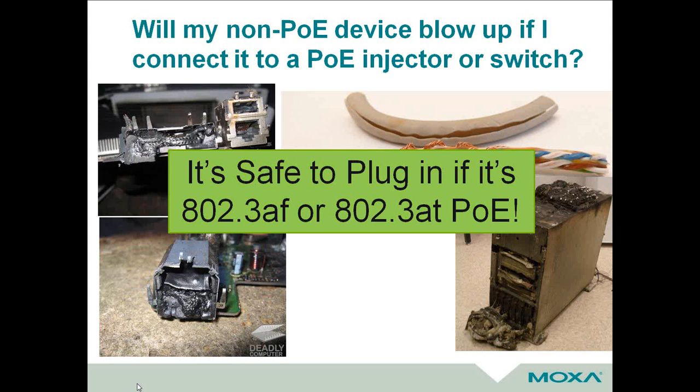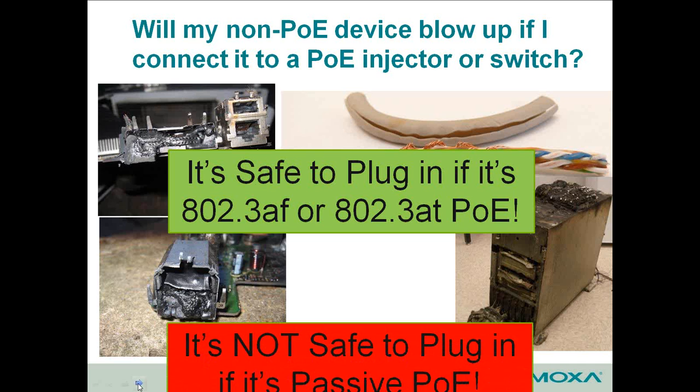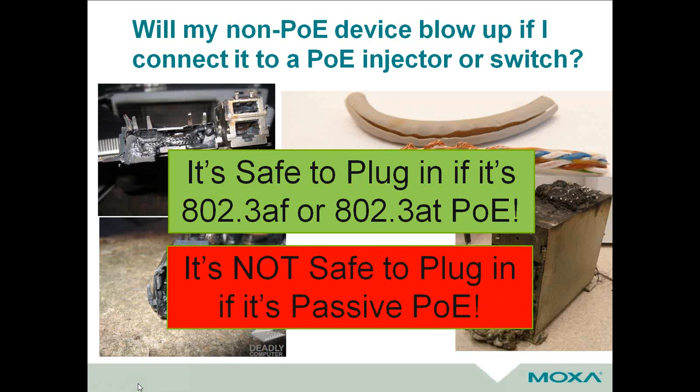So it is safe to plug in if it's 802.3af or 802.3at PoE. And the reason I say that is because some vendors have taken liberty in what they call PoE. Let me give you an example here. It's actually not safe to plug in to a non-standard PoE device, especially if it's called passive PoE.